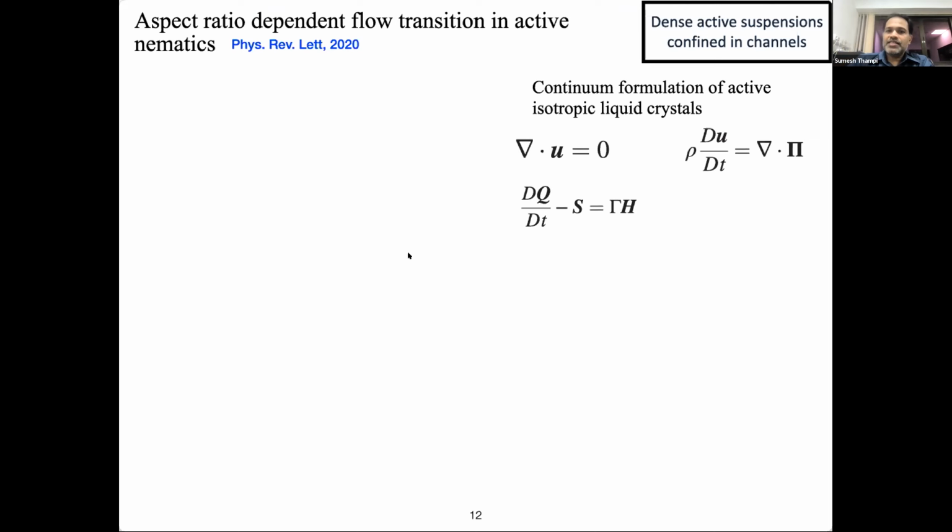So what we did is that we said, okay, we will just prescribe what is really required to describe the fluid flow motion. In other words, we say that the fluid conserves mass. The mass is not going to go anywhere. So that's what the first equation shows. The second equation is essentially Newton's second law, saying that force is proportional to acceleration.